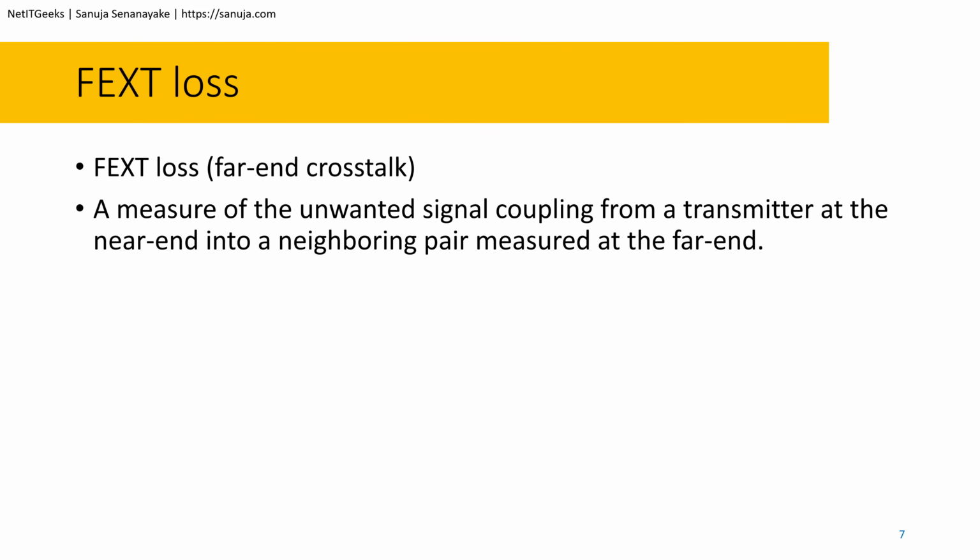The next one you should be familiar with for your exams is the FEXT loss, also known as the far end crosstalk. It's a measure of the unwanted signal coupling from a transmitter at the near end into the neighboring pair measured at the far end. Again, you need to know what causes the FEXT loss.